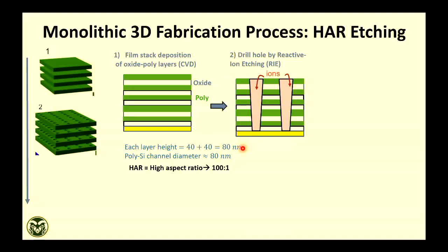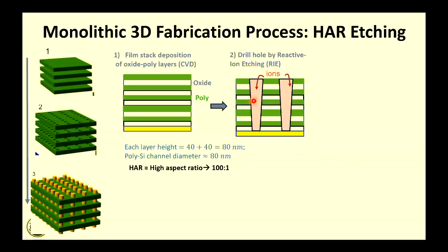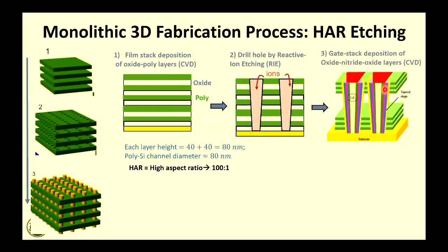Okay, so what is the last step? Last step, after you created that hole, you will deposit polysilicon, and I think that's what you were asking, right? So polysilicon will be deposited. It is not like you are starting with a crystalline wafer. A crystalline wafer is the costliest thing. It's a high-purity crystalline silicon wafer, which is sitting at the bottom, which is the yellow layer you can see. But on top of that, you are growing those metal and oxide layers. You are etching, and then you will deposit all those polysilicon and oxide layers.